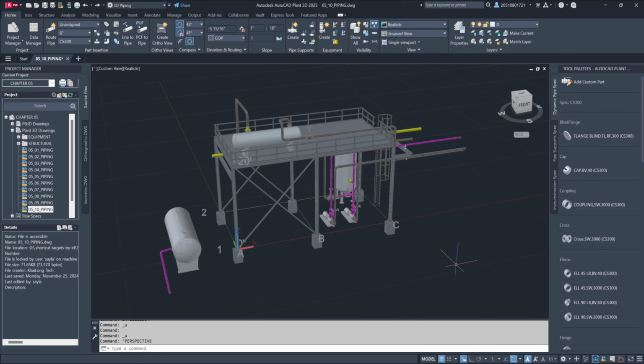When dealing with insulated piping in a facility, it is essential to indicate which pipes are insulated on the P&ID. This ensures that the insulation requirements are clear, allowing us to account for the additional material in our design plans. To add insulation to the piping, we specify the insulation thickness and type, as indicated on the P&ID, and include this information in the Properties dialog box.